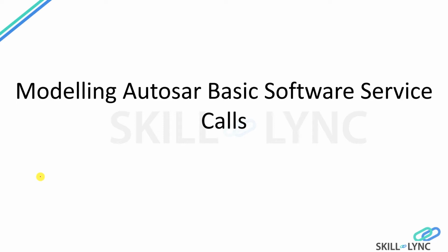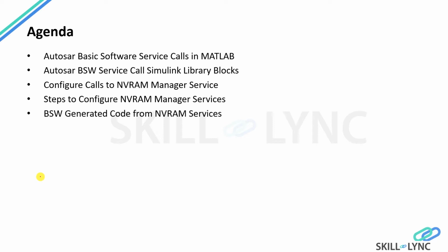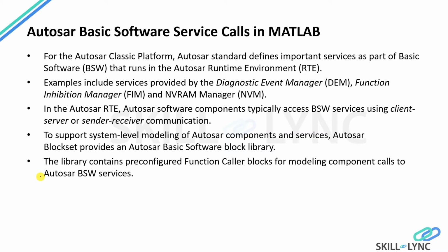This is going to be performed under the Autosar Classic platform, and we are going to do the whole thing for the Classic platform only, taking NVRAM related functions and blocks to implement this function. The agenda of today's discussion is the Autosar basic software service calls. The next one is the Autosar BSW service call Simulink library blocks. The third one is configuring calls to NVRAM manager, then the steps to configure NVRAM manager service related calls, and the last stage would be the code generation part. So now let's quickly move into today's discussion.